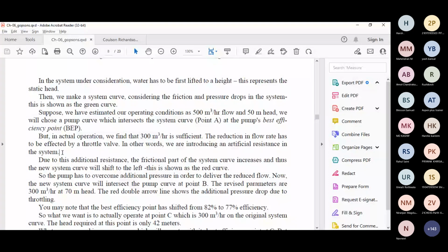अगर आप suppose there is a pipeline, आपका डिस्चार्ज का पाइपलाइन एक 4 इंच का है और एक पाइपलाइन है which is very less, suppose that is 1 inch, right? So what will happen in the 1 inch pipeline, your frictional losses will be very high because your velocity will be higher, right? So in that case what will happen, your power consumption will be higher, right? So that's why your efficiency will be reduced with respect to 1 inch pipeline.